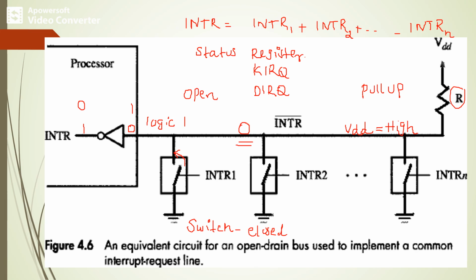If both keyboard as well as display have raised their interrupt request, among the two devices, one device will win the task and get the interrupt service, and the other device needs to wait for the service. The solution for handling multiple requests occurring simultaneously is known as arbitration.